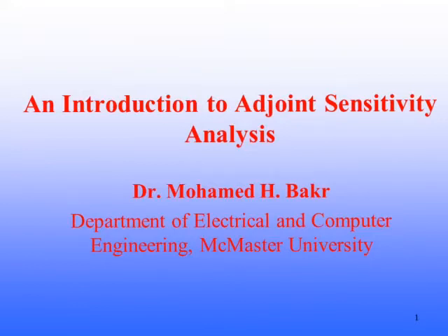And I will be discussing three main topics in this video: adjoint sensitivity analysis of circuits, adjoint sensitivity analysis in the frequency domain, and adjoint sensitivity analysis in the time domain.